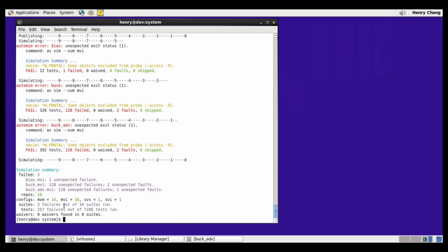In this case, we see an error in the bias block due to the inconsistency between the model and the schematic. However, there could have been a situation where there was a human communication error during the design of the bias block as to what the current to the ramp generator should be. The bias model and the schematic would have been designed to produce the same wrong output current, and the block level verification would have passed. This design error still would have been caught during a system or chip level simulation with the models.